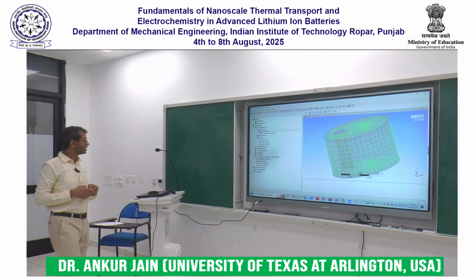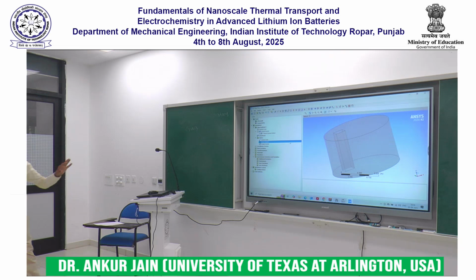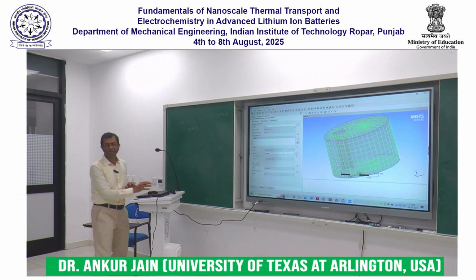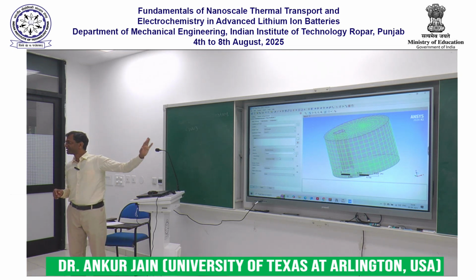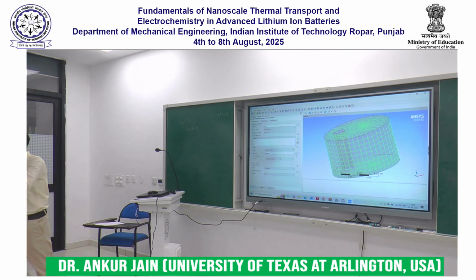Okay, so here I am now ready to define what things look like. I'm going to try and do this without the use of a keyboard, because we ran into trouble when we opened this. Okay, so let's see. I'm going to go inside and I'm going to say this is a solid body and the material is, say, copper. ANSYS by itself knows of only a few materials by default, but if you want, you can always insert a new material within.